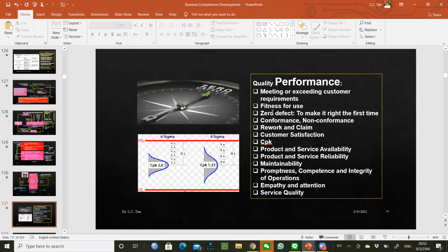And zero defects is our target, so you really have to make use of the CPK graph, right? You are trying to increase the CPK. The higher the CPK, the narrower the deviations, because your deviations shrink to a very narrow zone. That makes it possible to categorize your process into Six Sigma, right? And that is what we talk about: Six Sigma organizational capability, or Six Sigma operations process capabilities.